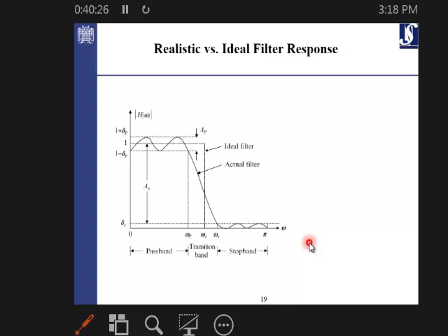Normally we have 1 if you want the signal just to pass through, and you have a margin that you allow for the filter to oscillate between these two margins. In general, we take those margins symmetric. Whatever you allow from the lower bound, the same size you have in the upper bound. The same margin you have for the pass or the stop band.